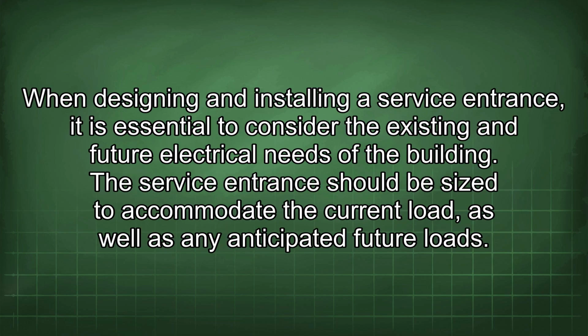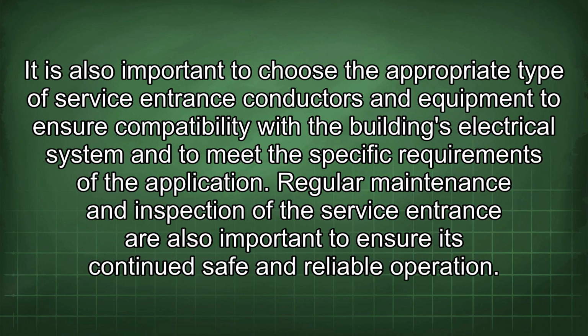When designing and installing a service entrance, it is essential to consider the existing and future electrical needs of the building. The service entrance should be sized to accommodate the current load, as well as any anticipated future loads. It is also important to choose the appropriate type of service entrance conductors and equipment to ensure compatibility with the building's electrical system and to meet the specific requirements of the application.